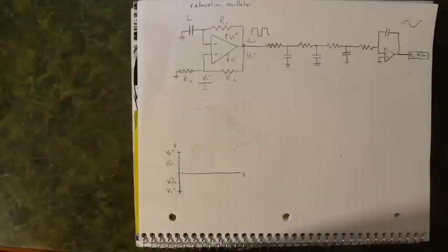There are a lot of ways to generate a sine wave controlled by a capacitance, and this is probably a very inefficient way to use a relaxation oscillator, but I chose to use a relaxation oscillator just because 6002X students should already be familiar with it. Other ways would include a Wien bridge oscillator, which would produce a sine wave, or a Colpitts oscillator. Those would be common oscillators used in a theremin. But nevertheless, let's just work through this. Let's try to find the frequency equation in terms of capacitance and the resistance.